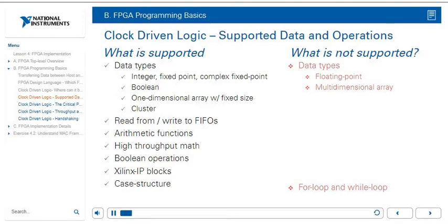In terms of the supported and unsupported data types and operations, in clock-driven logic, integers, fixed points, and complex fixed points are supported, in addition to Booleans, one-dimensional arrays with fixed sizes, and clusters, though the one-dimensional array functionality will increase to multi-dimensional arrays in future versions of LabVIEW Communications. You can also read from and write to FIFOs, both to the host and from the host, and between clock-driven loops. There are arithmetic functions, high throughput math optimized for low latency algorithms, Boolean operations, Xilinx IP blocks, and case structures so you can implement state machine-like logic.